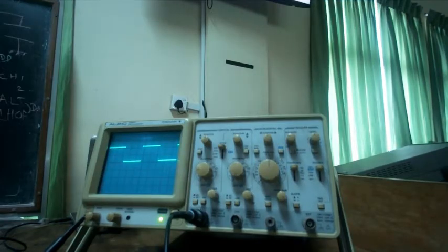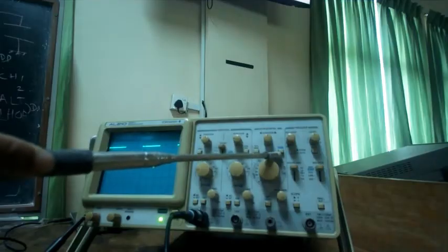Okay, so instead of this one being connected to the sweep signal, this is connected to channel 1, and the other one connected to channel 2. Right? Clear, right? It's clear. So that instead of with time, what it draws is between X and Y, channel 1 versus channel 2. Channel 2 is Y, channel 1 is X. Okay? So that's all it does. So you know this operation of this also.